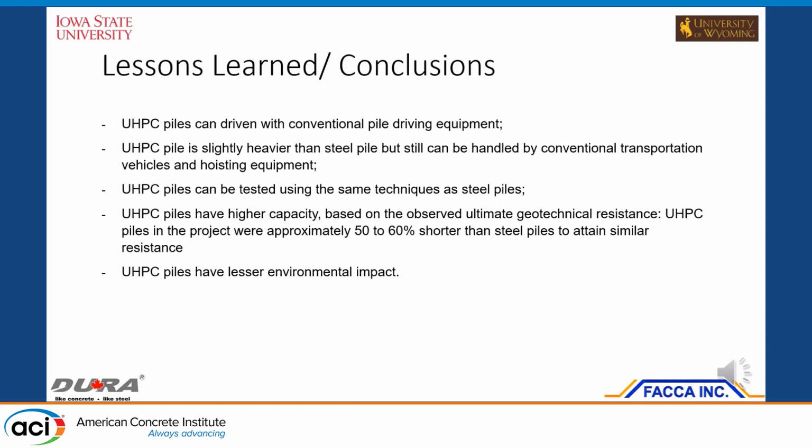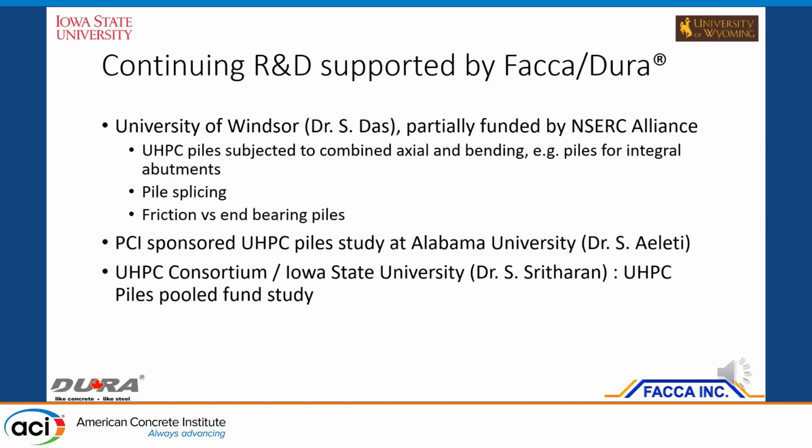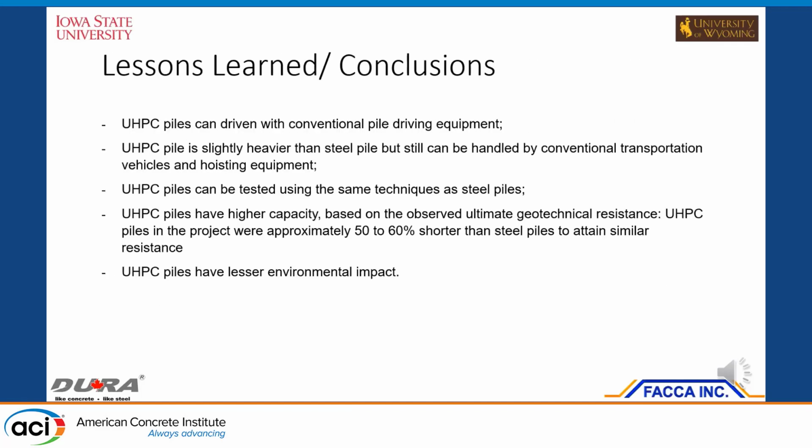And the UHPC piles have higher capacity. They were like 50 or 60% shorter than the steel piles to get the same resistance. And UHPC piles have lesser environmental impact. So the time to use UHPC piles is now.